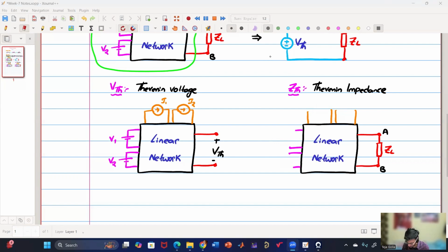Yeah, Dhanendra, you are right. So which is what we are doing. So first, we are not connecting the current source and we are short circuiting the voltage source. And of course, the load is not there. Now, calculate the net impedance across these two terminals. As if we are seeing from this terminal, what is the impedance that you see from this terminal? Meaning,